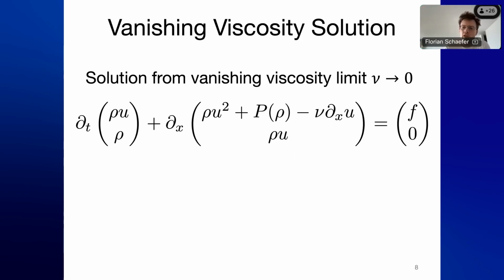As you have maybe noticed, these Euler equations do not have any viscosity, so they don't have a second order spatial derivative in them. The idea is really that we think of them as modeling the limit of infinitely small viscosity. Of course, every gas has a finite amount of viscosity, but we want to remind ourselves that this viscosity is so small that we cannot rely on it for numerical purposes. And that's why we take this idealized scenario of